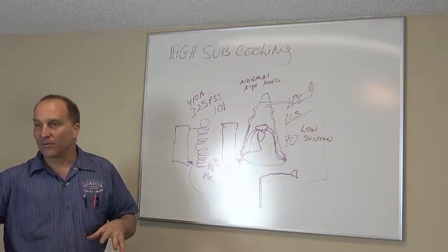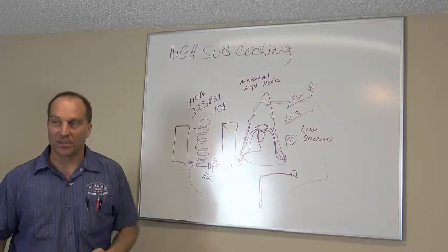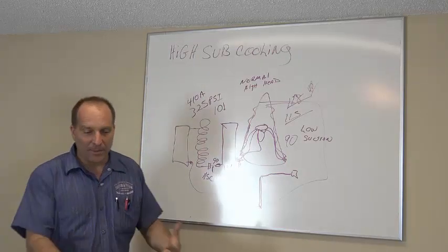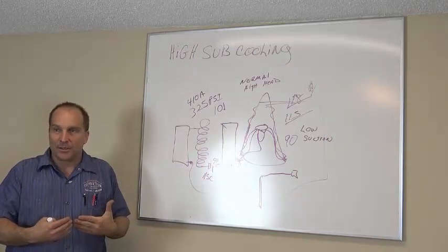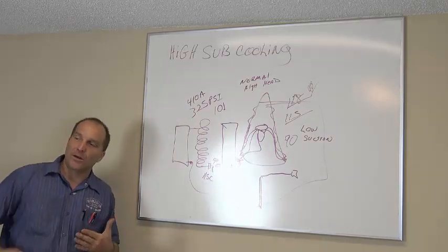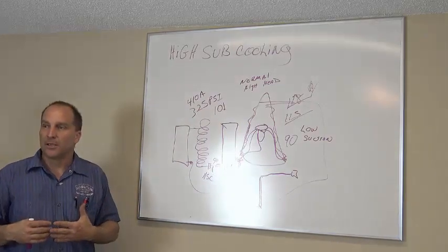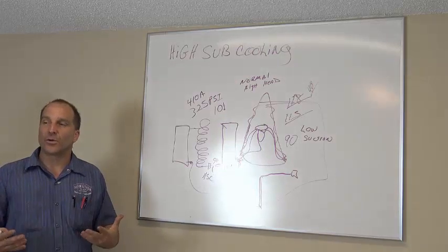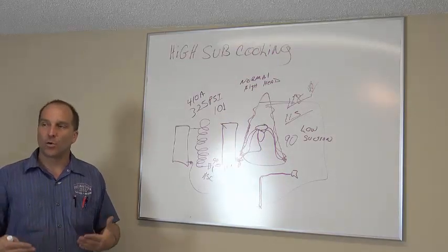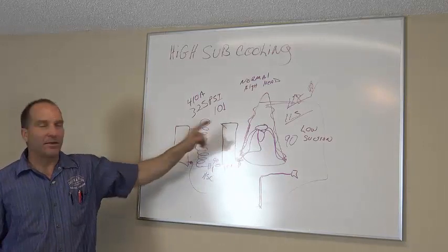So what is the condenser doing? It's removing heat from the house, bringing it outside and dispersing it, right? Well, if you keep that refrigerant in the condenser and the air keeps passing over it, it makes it colder, right? So you are cooling the refrigerant down more. You are subcooling the refrigerant down because of that kink.